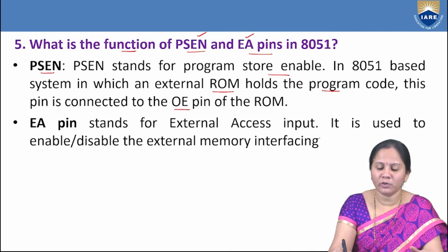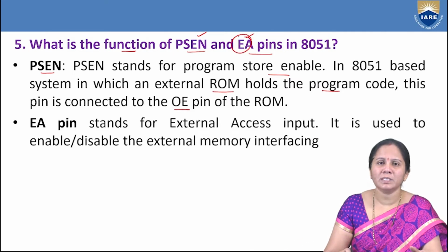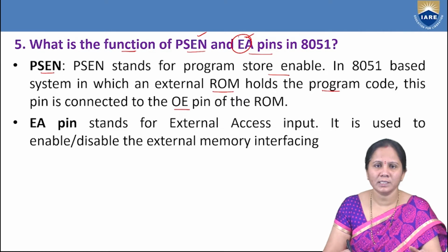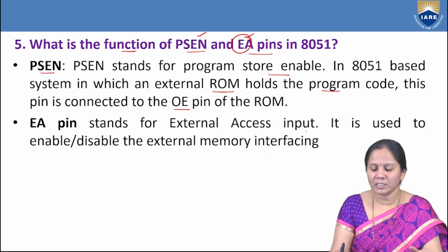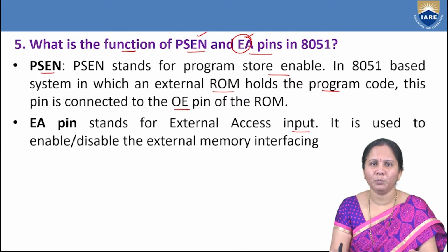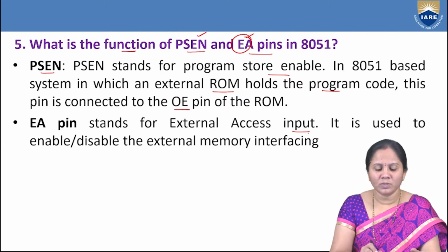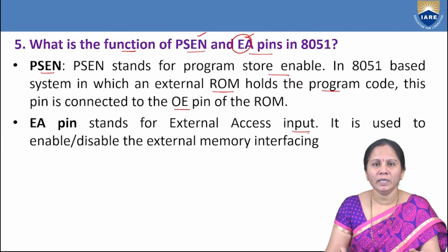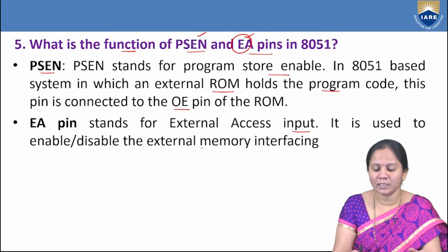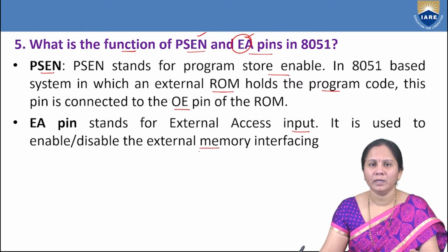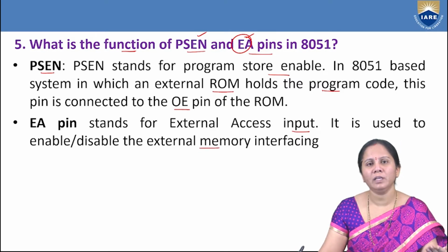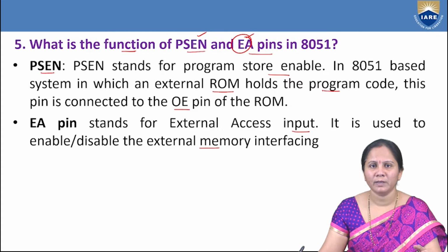And what is the function of the EA pin? EA stands for external access. It is the input pin. Using this EA signal only, it is used for accessing the external memory interfacing. So if you want to interface any external memory, with the help of this EA pin only it is possible.